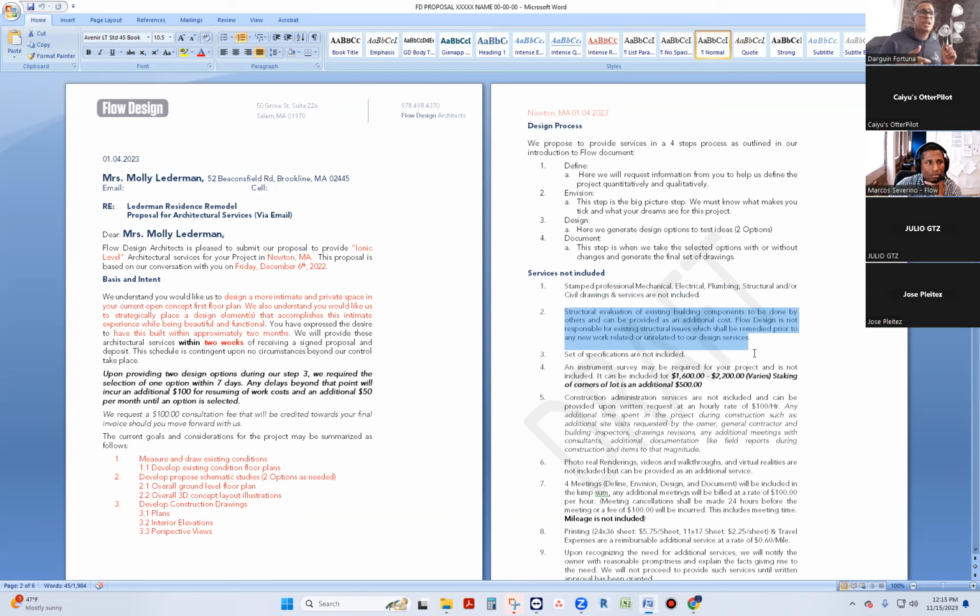Another thing that we've been doing, and Julio helped us, and actually is a pretty good case, is that we added additional footings. Why? Because we know that if this building falls, all of us are going to have to go to court and fight it in this deck, right? So we were like, you know what? You use all your 6 footings that you have. I'm still going to put 4 in my mind because we are protecting ourselves from additional liability, right? But we clearly said existing footings to be verified in field, right?